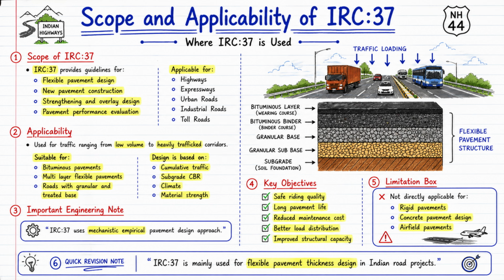Rigid pavements. Concrete pavement design. Airfield pavements. Now understand the practical thing here. Rigid pavement design is based on a different philosophy. Concrete slab behavior comes into it, the load transfer mechanism is different. Therefore, IRC 37 is mainly used for flexible pavement.